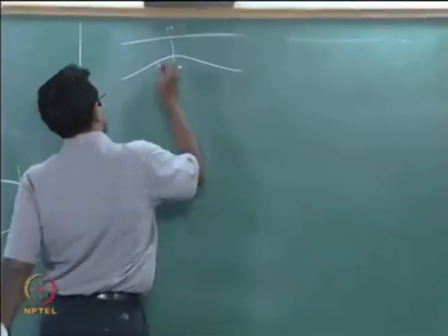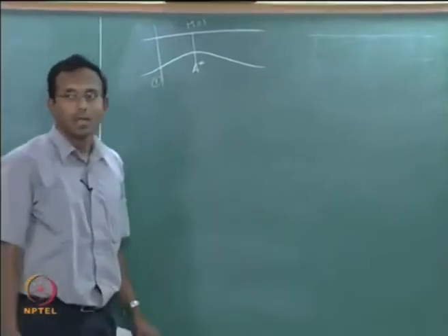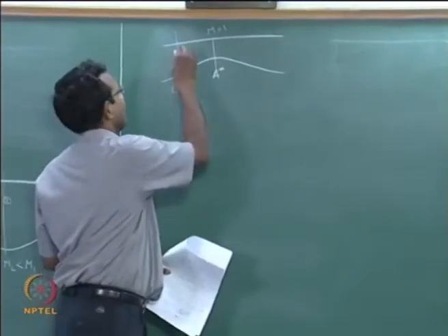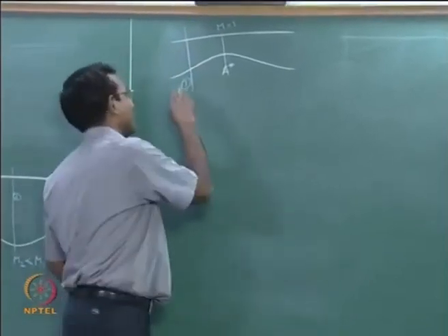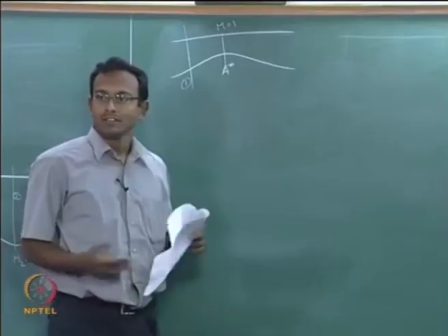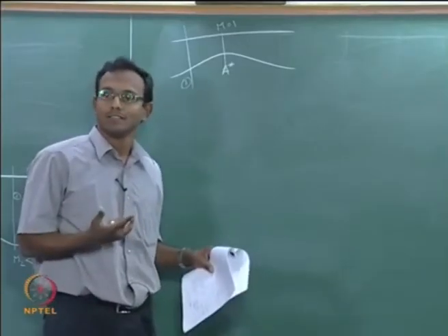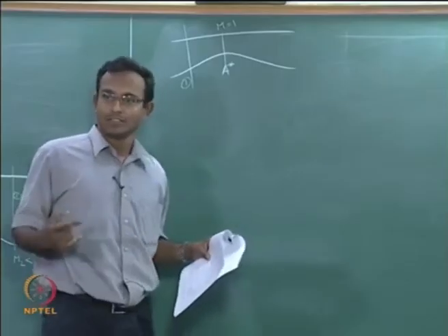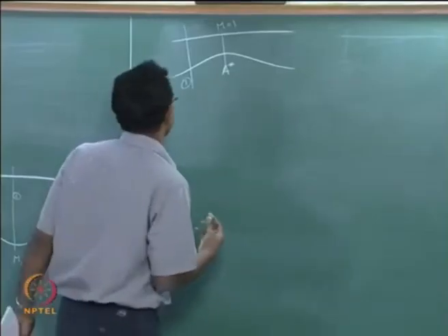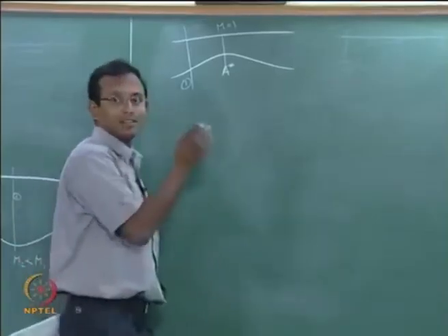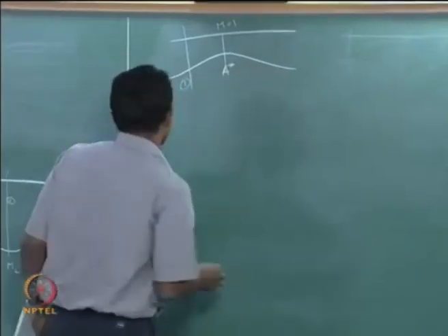Now our job is to go and find, let us say section 1, I want to know the Mach number for this area, whatever area A1 is given, let us say I want to find the Mach number M1, that is the overall idea. How will I find it? So now I will start using the integral equations and trying to get to some point where it will look like I know how to solve this problem. I have already assumed that it is an isentropic flow and I am starting to solve the problem. Okay.